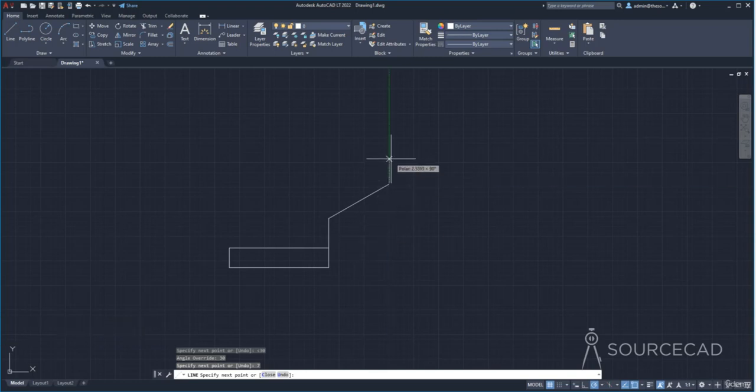Alright, now let's move it up and maybe add another distance here of 2.4 unit. There we are. And now I'll move it here and I'll add a distance of, let's say, 8 unit. Enter, and now you can add another angle if you want. In this case, we want another angle, and we want an angle of 150 degrees with respect to this line, again in anti-clockwise direction.